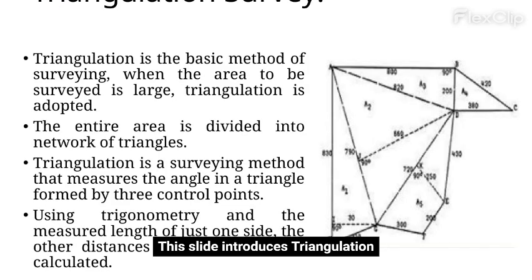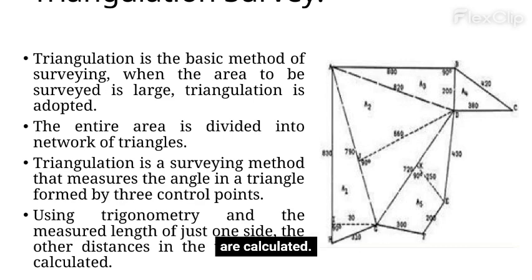This slide introduces triangulation survey, explaining it as the basic surveying method used when surveying large areas. The entire area is divided into a network of triangles, and the method involves measuring the angles in a triangle formed by 3 control points. Using trigonometry and the measured length of one side, the other distances are calculated.